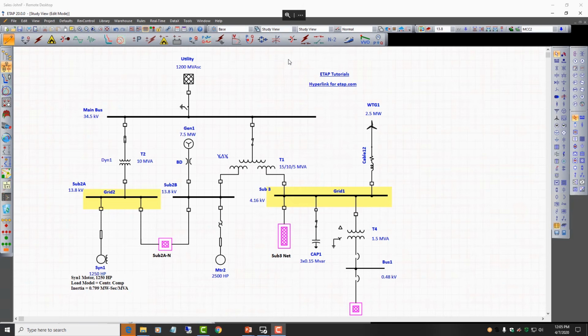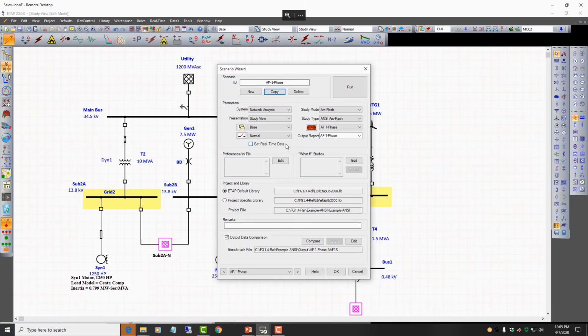And once it's time to run our studies, we could take advantage of our scenarios. And incorporated in the scenarios is revisions that manage all the electrical data properties that you can alter and have unlimited layers. You can change cable lengths, transformer taps, anything you like, and incorporate it into an electrical revision layer. Configurations, which manages the status of protective devices, switches, open and closed, which position, and mix and match any for all of the study types provided in ETAP and run it through our scenario.